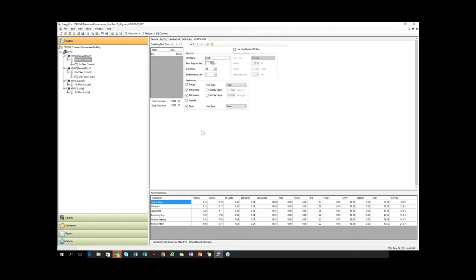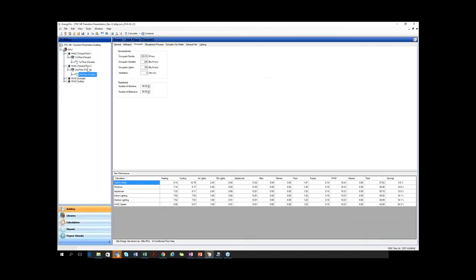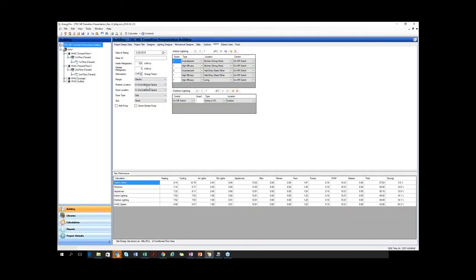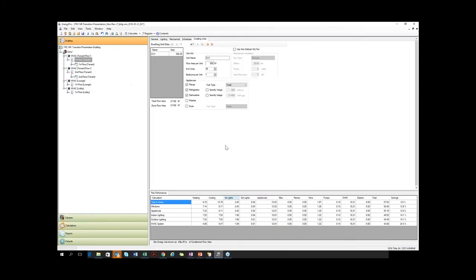And also from the HERS tab, you could come down and replicate these things. There's no washers and dryers in the units. We could check our EnergyPro 5 model, see that there's electric range, and do the same thing on each floor. So this is the same unit type, except there's 38 on the 2nd floor.